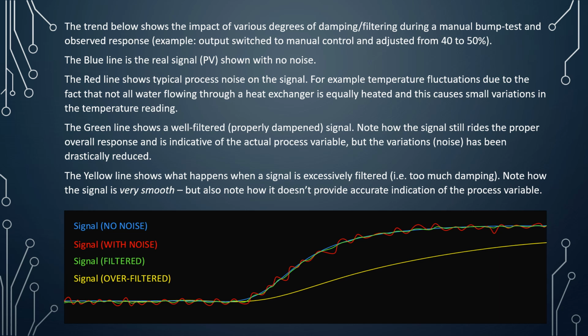So that's a real safety issue, and it also causes all kinds of challenges with process control. If you've ever entered too much damping in a transmitter, you will instantly know because a lot of times your loop tuning goes out the window and the process runs really, really bad until somebody hopefully comes in and figures out what happened. And they tell you don't do that again.